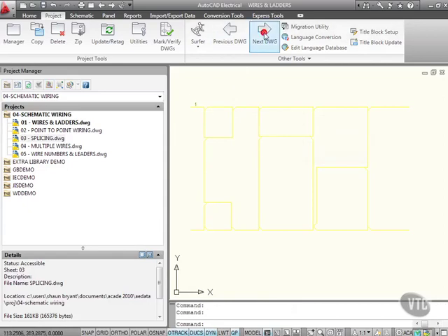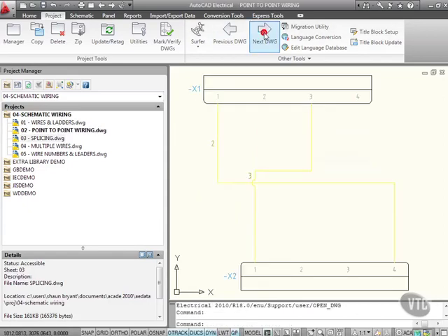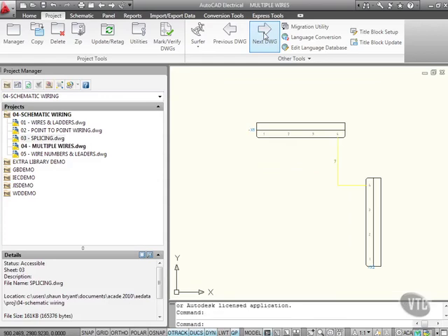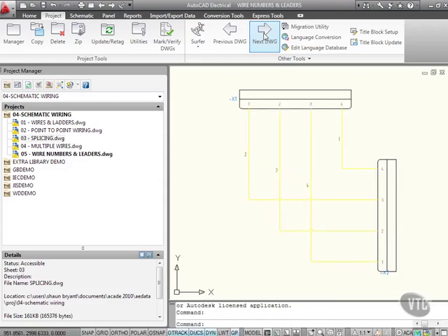There's 1. If I go to the next drawing, 2 and 3, 4 and 5, there's 6 there as well. That's 7. And then when I get to here, 1, 2, 3, and 4. Because, obviously, I've done those separately already. But because I set that sequential for project wide, it started at 1 at the beginning of the project on the first drawing, wires and leaders, and then worked its way down to multiple wires there. So as you can see, wire numbers and leaders, quick, effective, all the tools are there in AutoCAD Electrical for you.